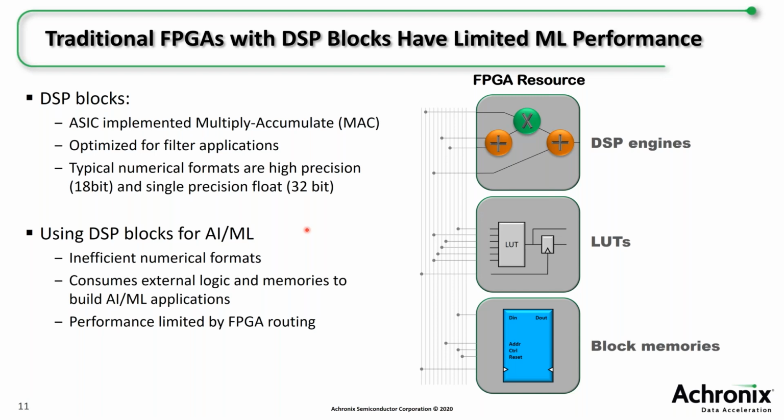Second of all, you need a bunch of external logic and memories to build the application itself to connect everything up. And then because everything is connected up by FPGA routing wires, the performance is generally limited by the FPGA routing rather than any of the other functions.